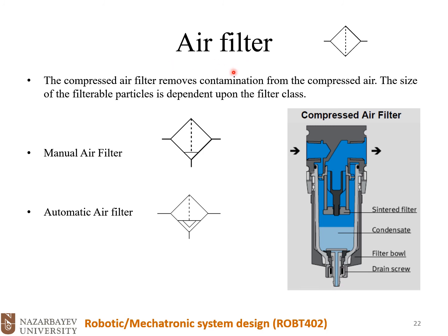Air filter. We need to filter any dust and obstacles. We don't want to send those obstacles to our moving parts, directional valves and cylinders. Those are expensive parts. Plus, they could destroy our system, and they could increase the friction.